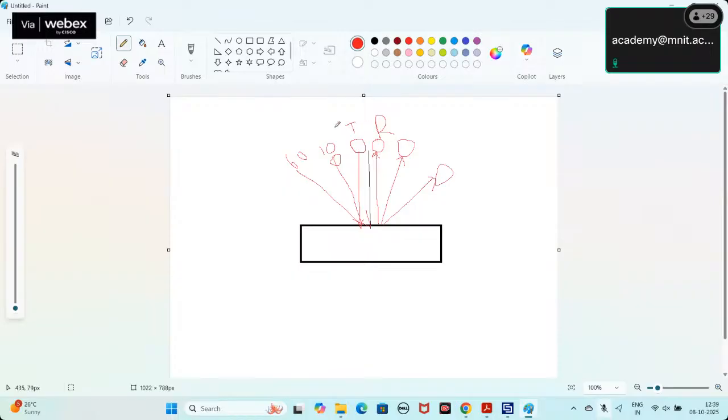That means as theta increases, you have to place your antennas accordingly. In CST, it will directly handle all these things. When you select theta 0, theta 80 or theta 50, it will automatically shift both the ports accordingly. But in practice, you have to take care of these things. Theta will go like this, so your transmitting antenna will also go like this, and the receiving antenna will also go like this.